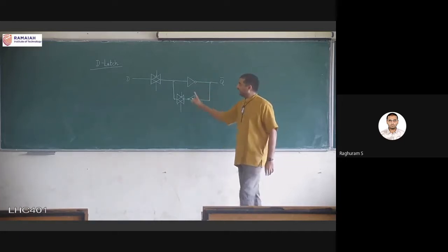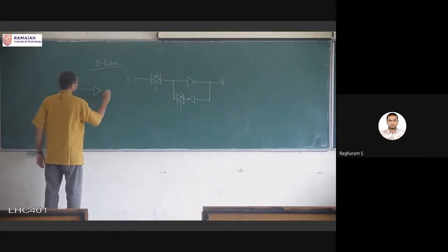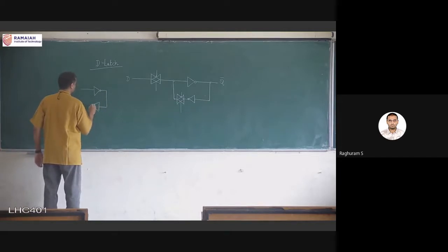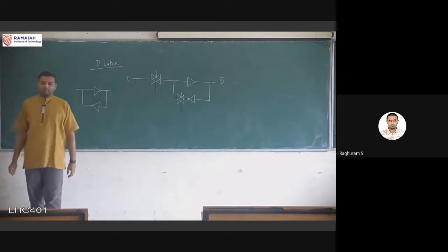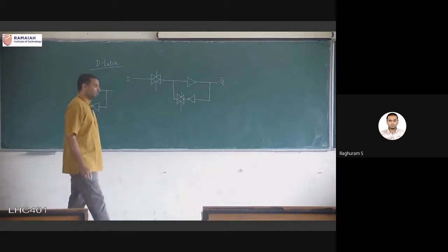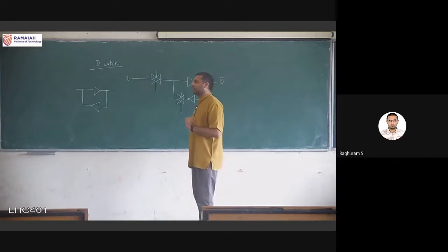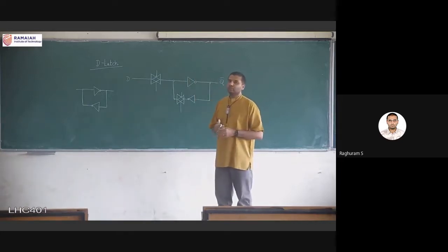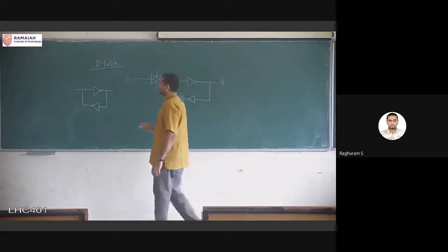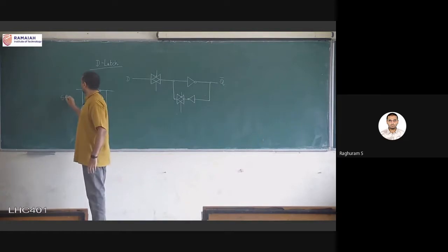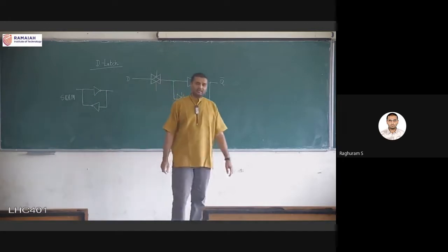So this back-to-back inverters is among the fastest, not the most common, but the fastest way in which the memory circuits are implemented. And this circuit also forms part of what is called SRAM, or static random access memory.